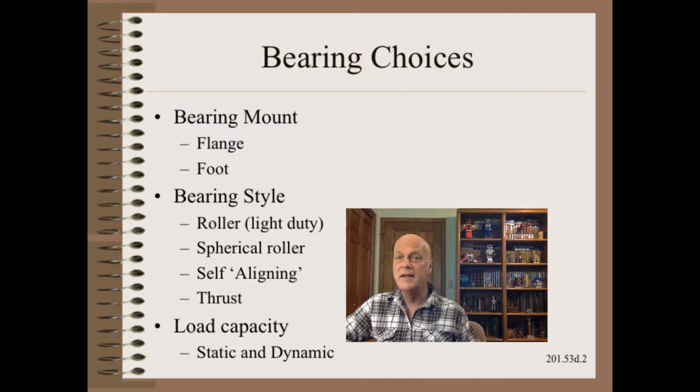Our second choice is what basic style of bearings we are going to use. This largely depends on loads and misalignments. By loads, we mean radial and thrust. Many people do not know that rollers in a nip can see upwards of mu times N force, where mu is the coefficient of friction between rollers and N is the nip force.